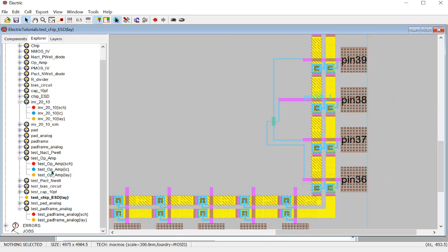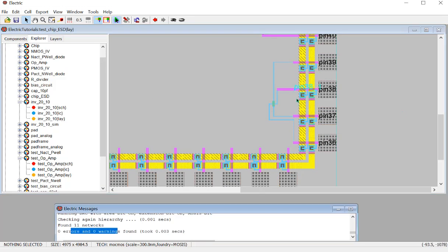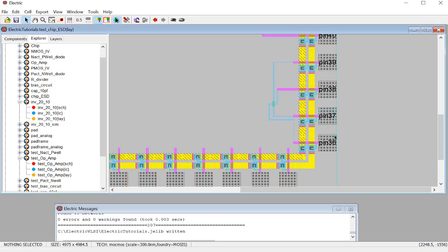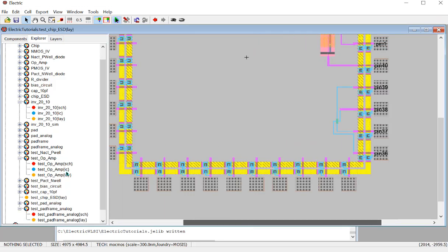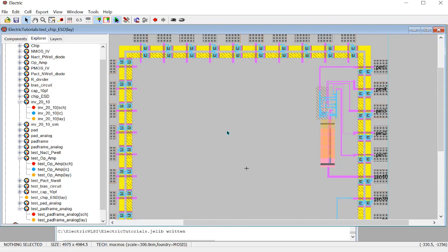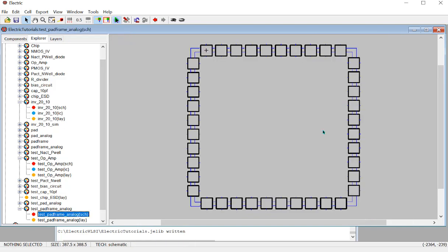So let's get the schematic work as well, because I press I5 and there's no error pops up, so it's clean. So the only thing left for the entire project, we're super close to get this done right now. The very last step is just to place the op-amp and the inverter into the schematic.